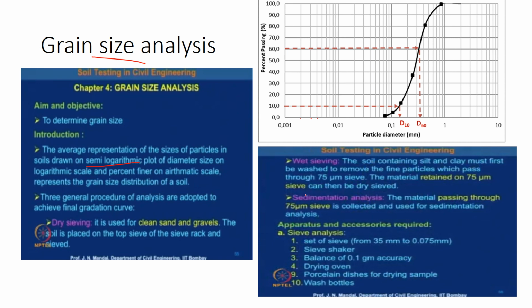For a soil, and I'm not talking about gravelly particles here, when they bring the raw soil to the lab directly from the field to perform the grain size analysis, we will take around 500 grams or 1000 grams of soil. It's up to us. Take 500 grams of soil and soak it in water for 24 hours.